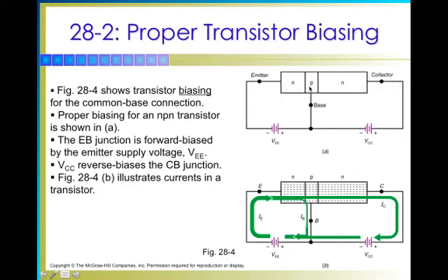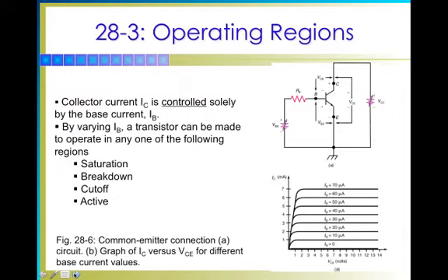Draw the picture of a regular diode, which is the N and P, and then add an N to it, which is the collector side. And just go ahead and do the diagram for what we have normally done with the normal diode. And then just add the collector on it, and notice that the collector is always going to be reverse biased. Okay? That's how you can learn this one fairly simple.